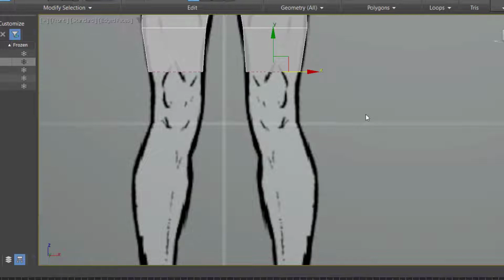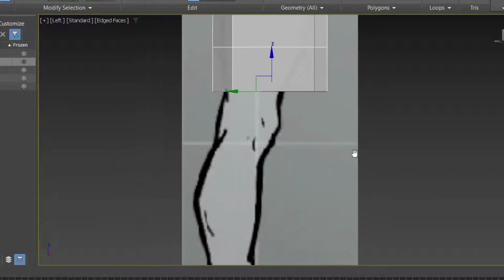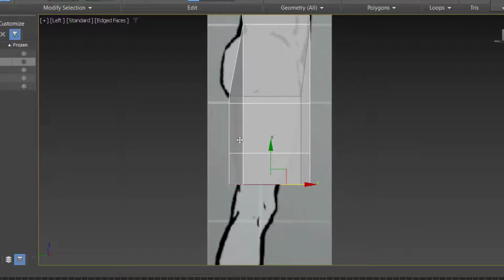So in doing polygons for the knees, we have to anticipate animation also. So in anticipating the animation or movement of this, oops, I'll go to my side view. And this is where I will encounter, let's say, not really a problem, but a situation wherein the polygon doesn't look regular, or it's unfamiliar looking. So it's supposed to be flat and straight lined. So what I will do is like this.